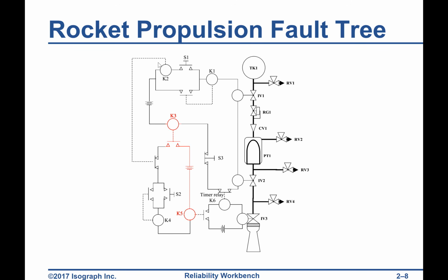They could if they failed. You could have an arbitrary failure of K2 that opens it. But one of the rules in the fault tree, if you read that little math handbook, one of the rules that they give, which I think is a good rule, is no miracles. For instance, if K2 just happened to fail and open when it's not supposed to, right when the cutoff is supposed to occur, you'd be saved, right?